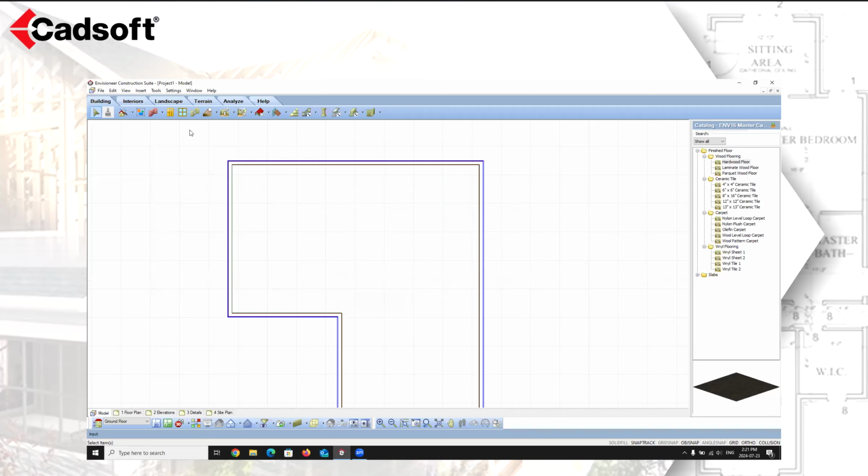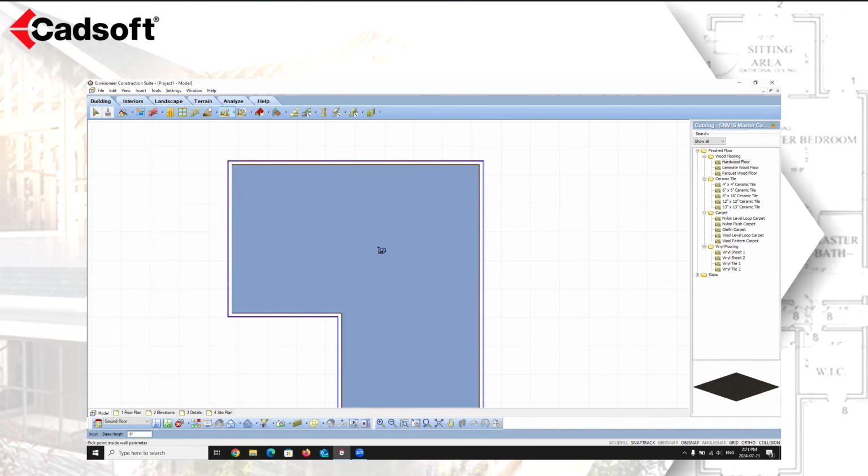So what I'm going to do here is, again, select that floor by room, select my hardwood, and bring it into my design area. And instead of just entering in a base height of 0, I'm going to type in a base height of what I feel the thickness of that floor should be. This can be the thickness of the underlay material as well as the thickness of the floor itself. You can make that decision. I'm just going to go up 1/4 of an inch.